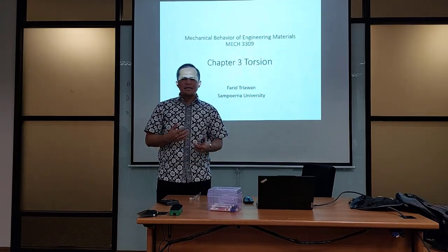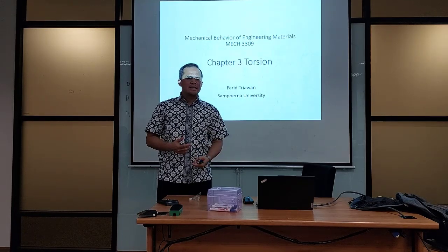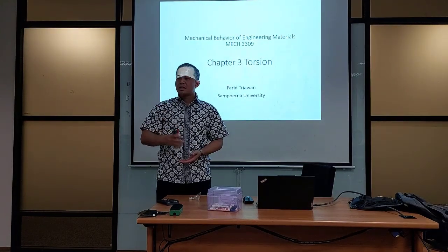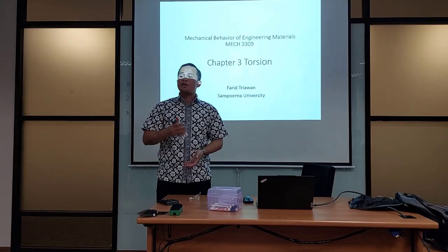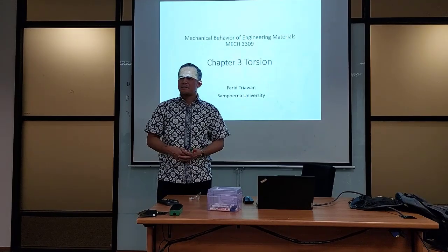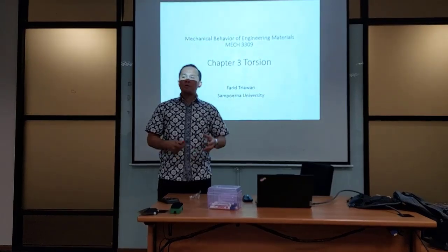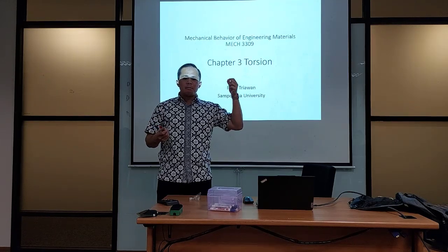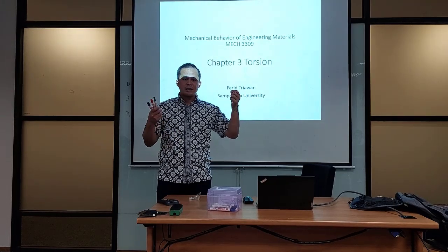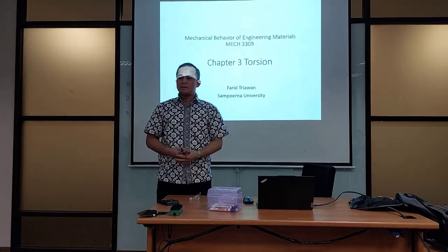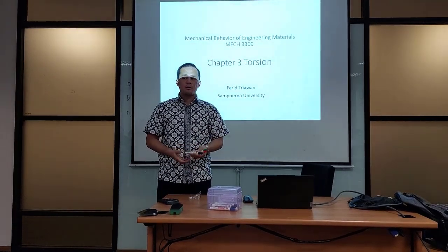What are the similarities between normal stress and shear stress? The formula is force over A. It's always force over A because stress is in Pascal. Pascal is Newton over meter squared. So you should be aware that no matter what mode of loading your specimen is subjected to, your stress will always be in Pascal, Newton over millimeter squared or meter squared.